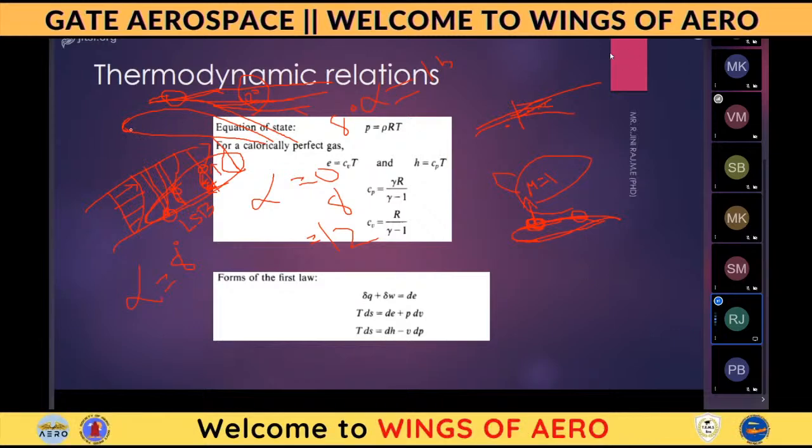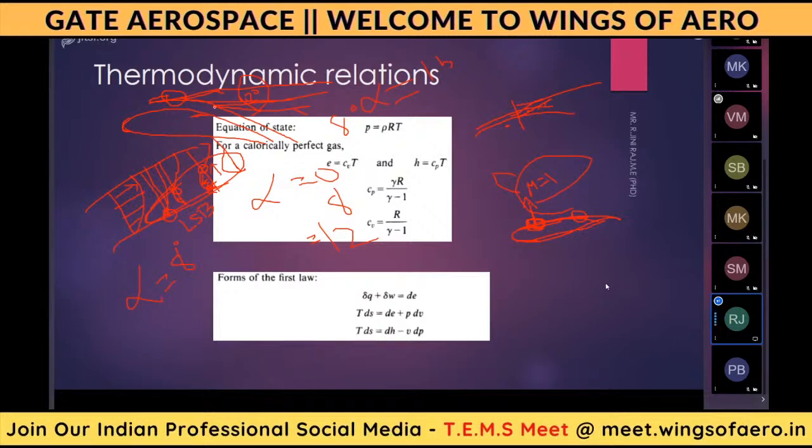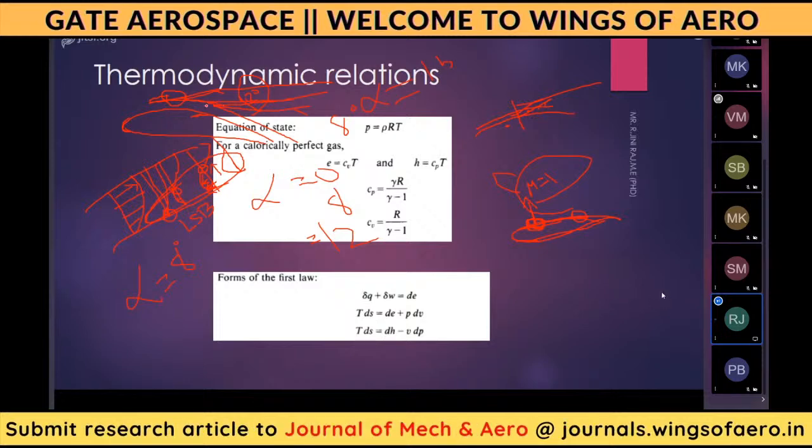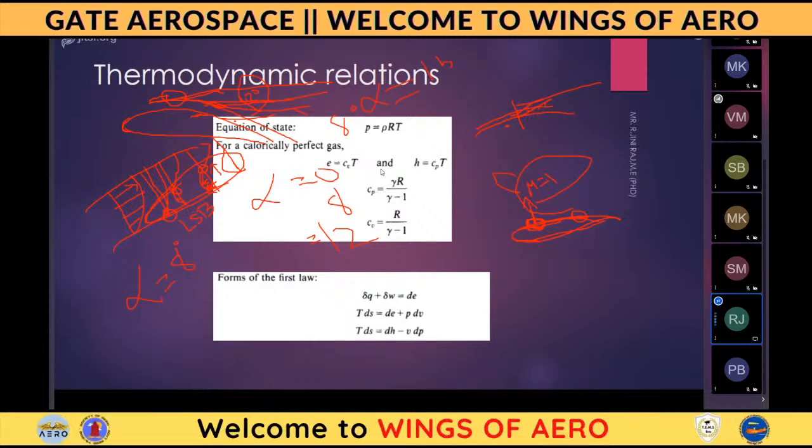They will be changing the thickness also, and some will pass a jet of air over the surface of the airfoil where the stall occurs. So where the separation starts, it will move somewhat backward. Some will use a morphing concept. They will be using morphing concepts or some other techniques for delaying this stall.